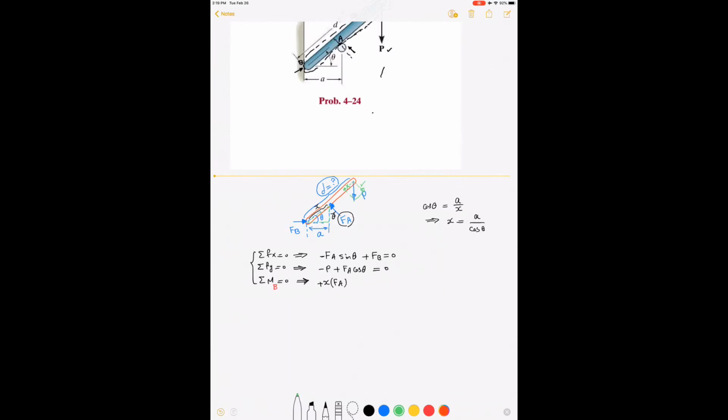Alternatively, you can move this force down, and at this point we bring it right here. So the moment arm is from here. Let's use another color. The moment arm will be from here to here, which is d cosine theta, right?